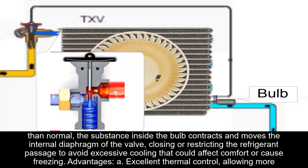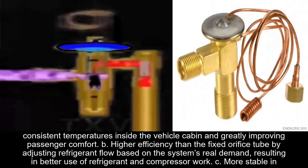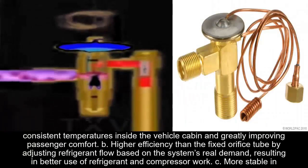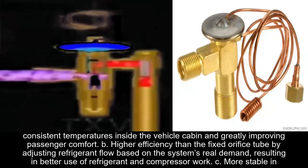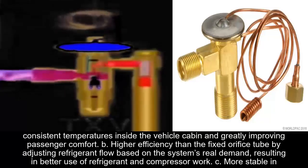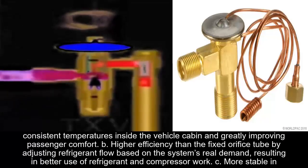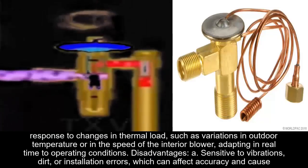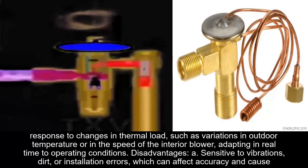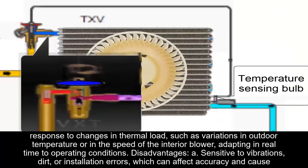Advantages. A. Excellent thermal control, allowing for more consistent temperatures inside the vehicle cabin and greatly improving passenger comfort. B. Higher efficiency than the fixed orifice tube by adjusting refrigerant flow based on the system's real demand, resulting in better use of refrigerant and compressor work. C. More stable in response to changes in thermal load, such as variations in outdoor temperature or in the speed of the interior blower, adapting in real time to operating conditions.